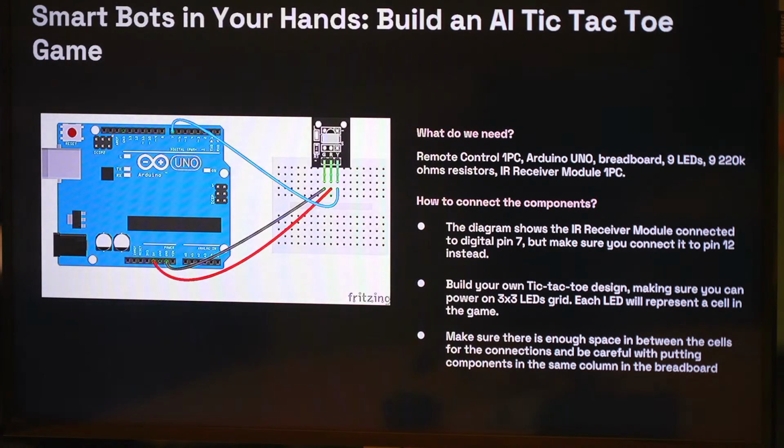Okay. So we got, for example, remember the shorter leg is the negative? Yep. So this one we're going to be using for the positive. So we just want to use the resistor. You can save one wire by doing just this, literally. Then you just connect this one to the digital pin to feed the positive. Got it? And then make sure you map it.